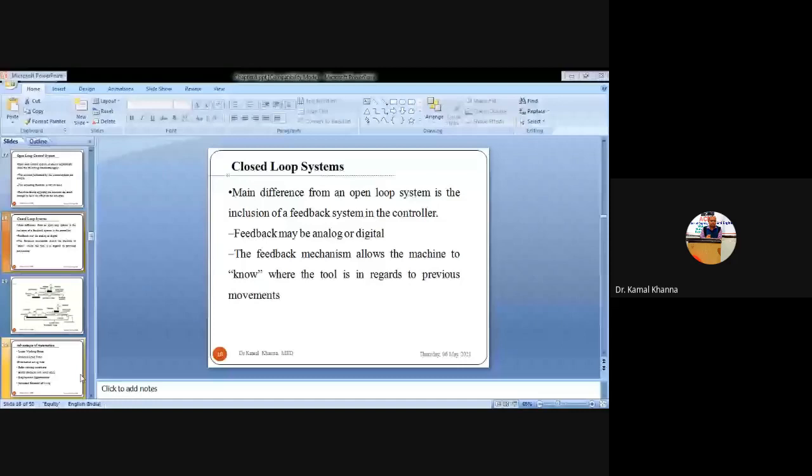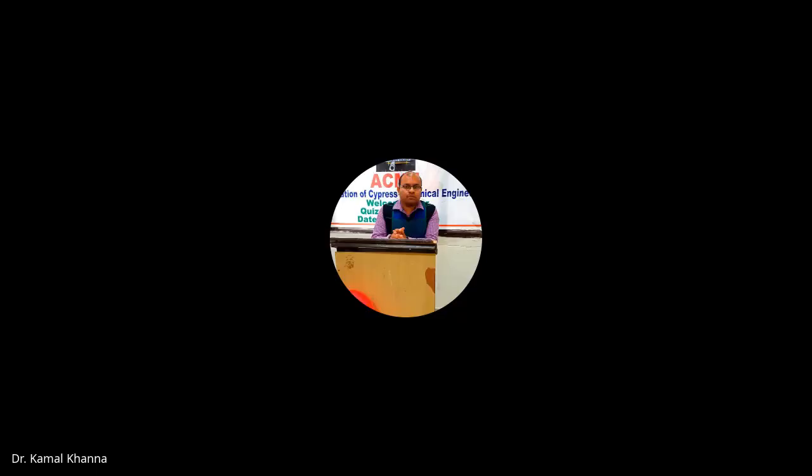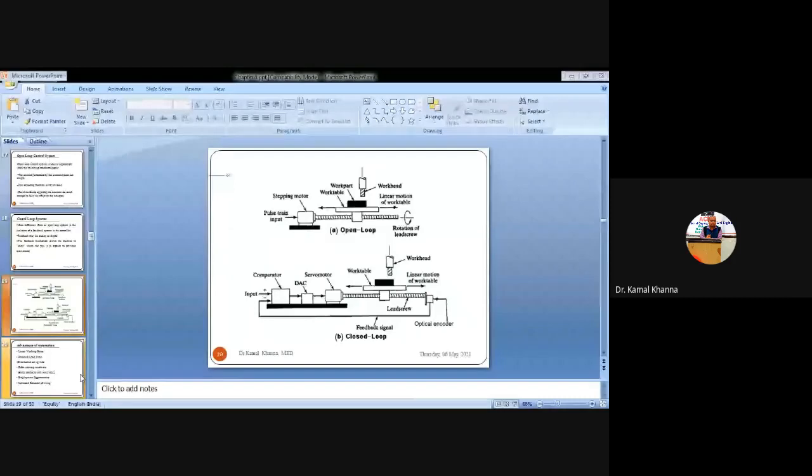Feedback also allows the CNC machines to know what is currently going on in the machine, what the next course of action is, or what the next position of the tool is with respect to the previous positions, and whether it is happening correctly at the cutting zone. It also tells whether the operation being performed by the tool has fetched the correct tool, and whether the direction, shape or position of the specimen is correct or not.